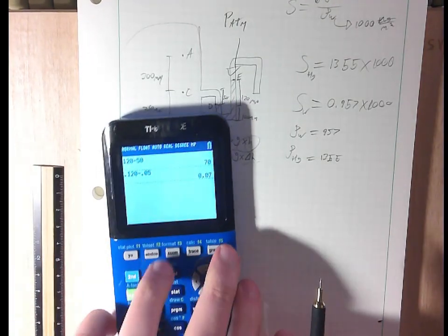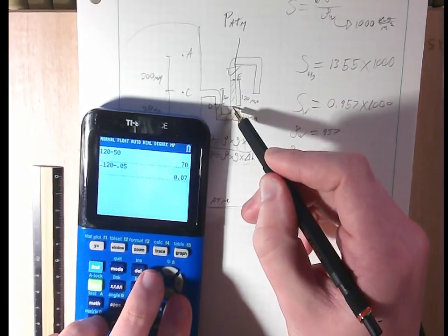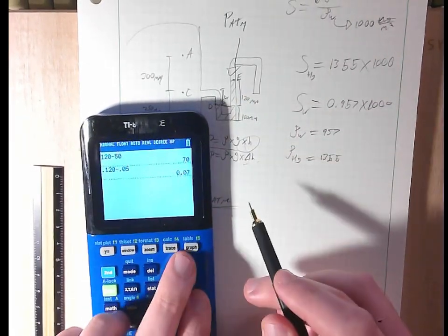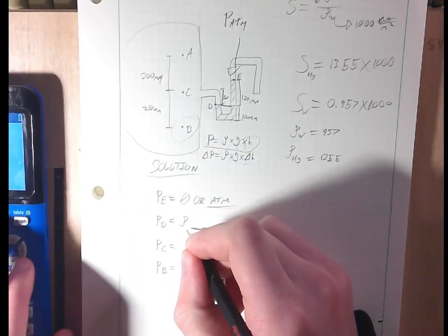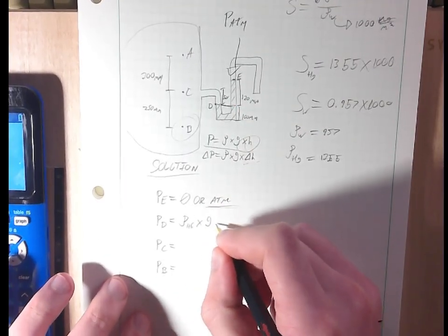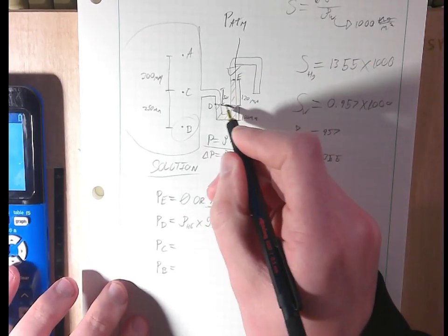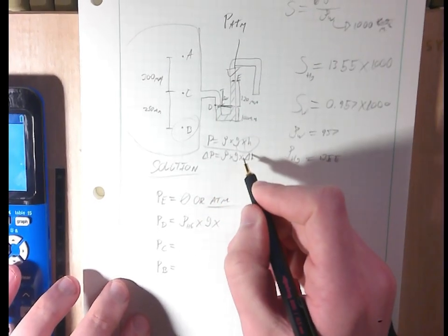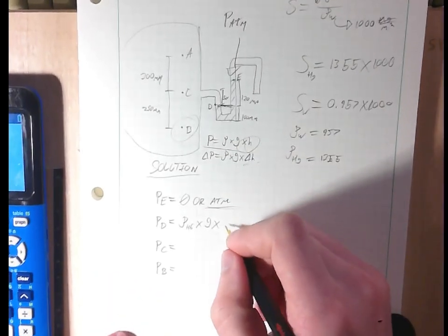Sorry, it is not. These are the same height. I just drew it poorly. My apologies. So what this is going to be is rho of Hg, because it's mercury right here, times gravity, times H. And the H is, sorry, is actually just 120. If I was doing to C, it would be different, but we're not, so don't worry about that.